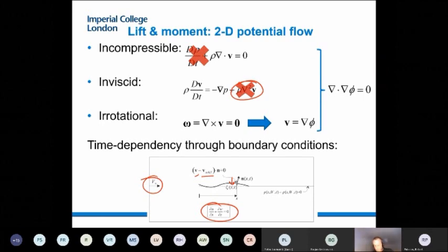And then to close the problem, and this is a fundamental feature of airfoil aerodynamics, you have two different flows going on top and bottom of the airfoil as you go down the airfoil, which don't talk to each other. So when they meet at the end, they will meet at different speeds in terms of tangential speed. You should expect that to happen. So what we have is a discontinuity which is not accepted by the potential flow equation.